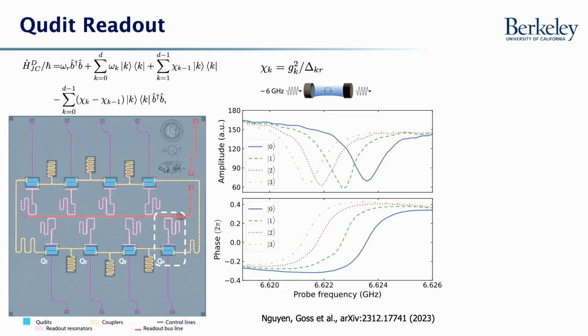OK, so how do we do basic readout at, say, the single shot level of these qudit devices? Basically, we just couple this transmon circuit to a linear element, which is just an oscillator. And this effectively realizes a generalized Jaynes-Cummings Hamiltonian, where the amplitude and phase response of this linear oscillator on our chip is dispersively shifted based off of whatever state our qudit is in.